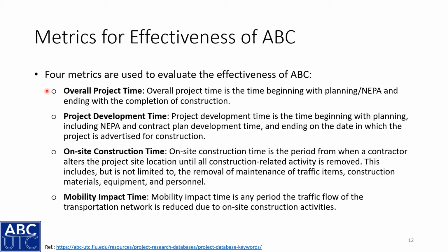So for an emergency replacement, if a bridge gets wiped out due to a flood or fire, something like that, or a bridge hit, then decreasing the overall project time becomes one of the more important parameters.